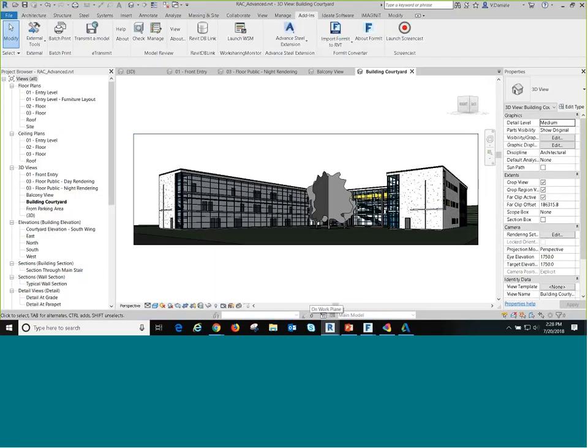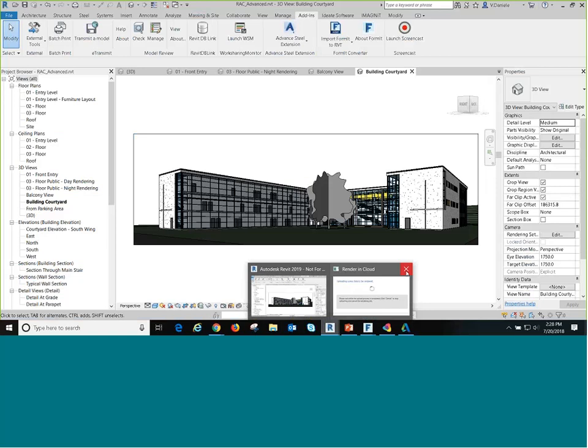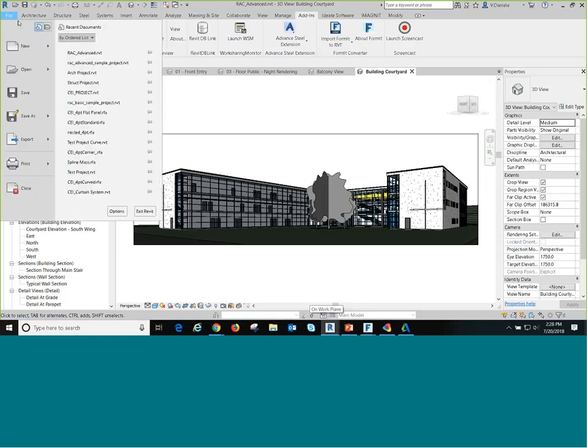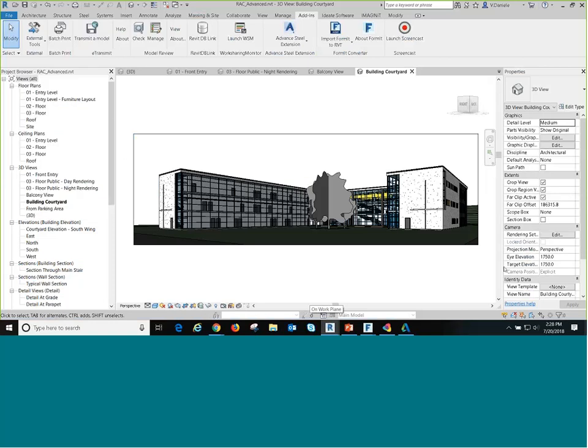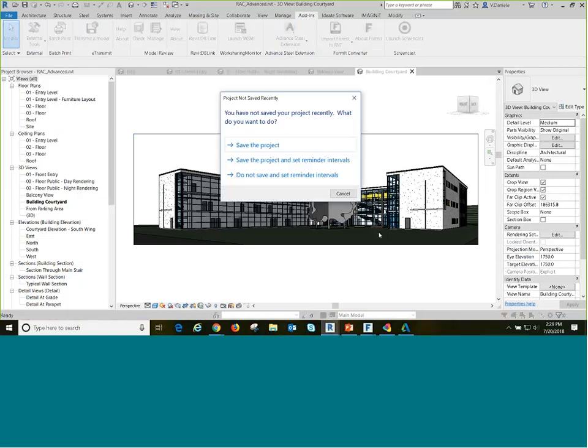And then right from there, inside of Revit, let's go to a new conceptual mass. I could do this right at the project level. I just prefer, if I'm applying any different materials or anything, I like to have everything kind of packaged into one family file. But you can bring that massing right in and it kind of sees it. I think it actually does make it an RFA file, but you have a little bit more tools to use once it's in a conceptual mass.